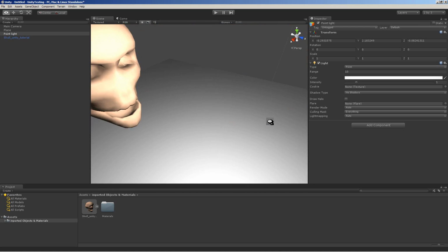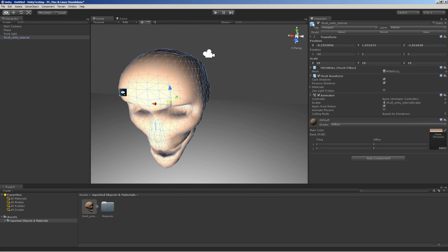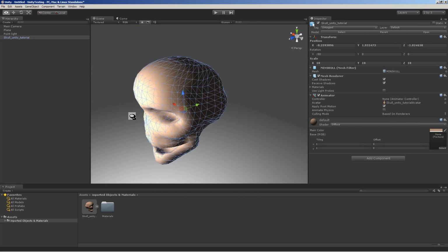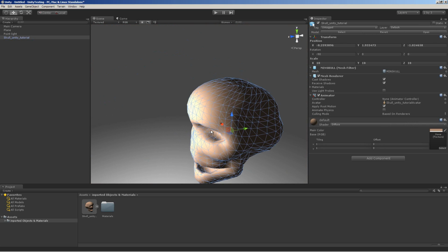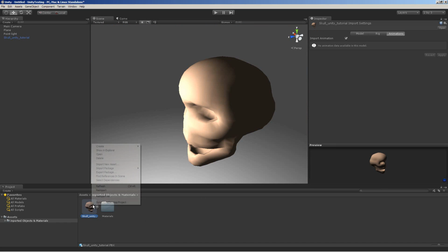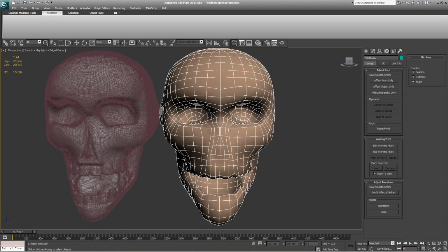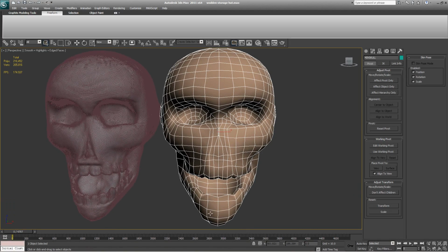This is called normal mapping. However, this is a low polygon model. We've done a very good job on simplifying that high polygon mesh, so we can use this low polygon model in our games. And let's jump back to 3ds Max for now and delete the skull for now as well, because this skull at the moment doesn't have any UV coordinates mapped out. And following the techniques of the second tutorial, we need to map out the skull using the unwrap modifier.